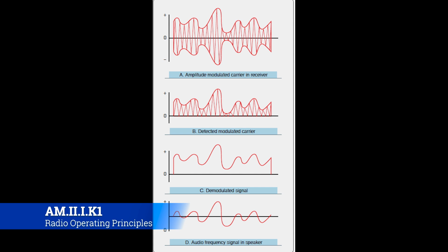As that happens, it just goes across the world, I suppose, and then hits the radio, where the exact same thing happens but in reverse. Now you have a wave that's coming into the radio, gets stripped of the carrier wave, and all that's left is the little pulses that the original microphone had placed into that wave. That comes out of the speakers, because it moves a little magnet up and down, which moves a diaphragm, which then produces vibrational waves in the air, which we then hear as sound. It's really not that overly complicated, but that's how AM and FM modulation and demodulation work.